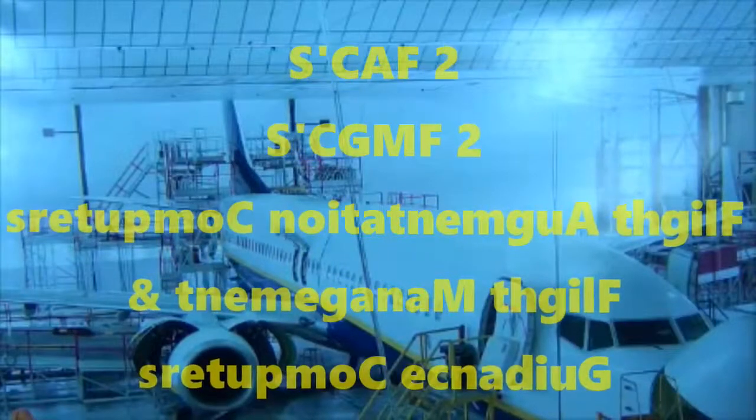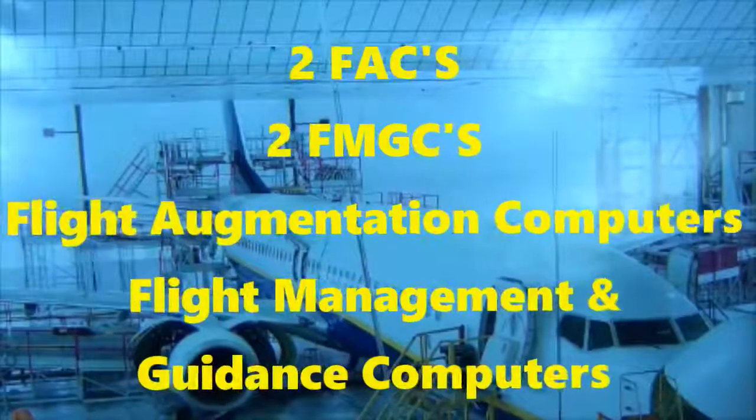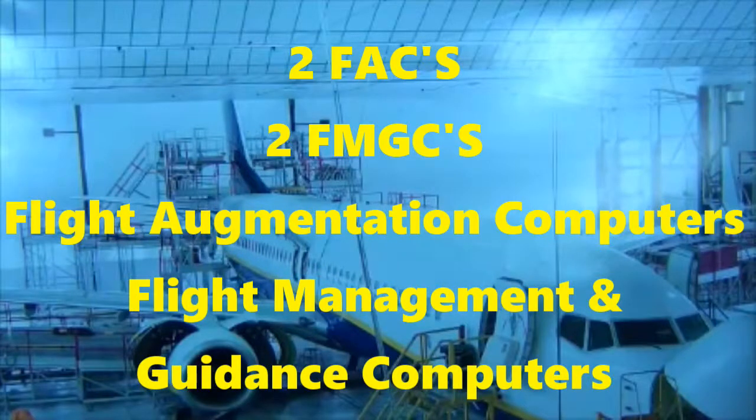So those are what you have: 4 computers, 2 Flight Augmentation Computers and 2 Flight Management and Guidance Computers. So in a nutshell, what is its function? What is it controlling? There are 2 parts to this. You have the management part and the monitoring part, and it's constantly getting the inputs in order to give the orders for the control of flight control surfaces and also for engines, because when we get to power plant, we'll be talking more about FADEC, but that is basically your control brains for the engines.